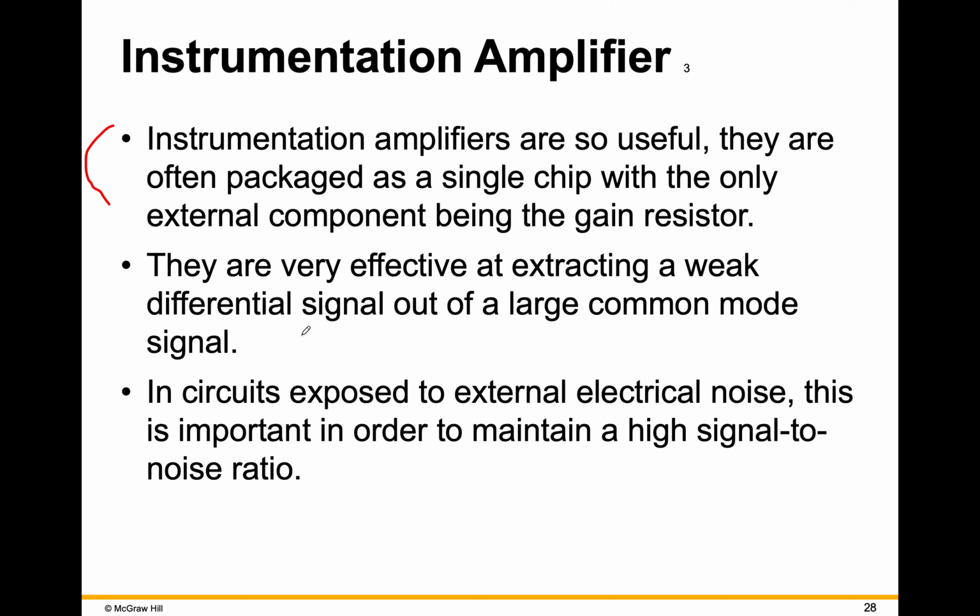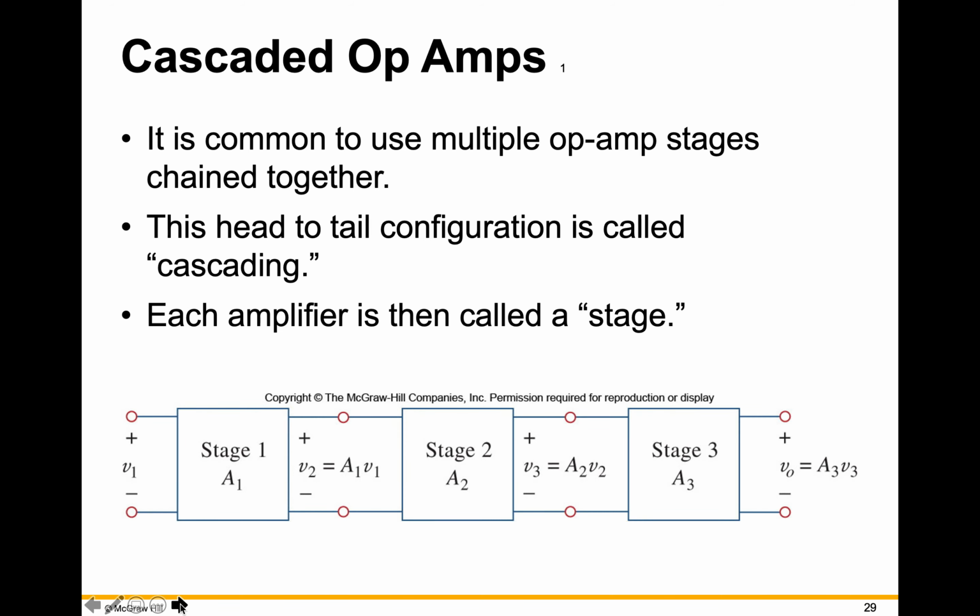So the hope is that the large signal is common to both probes, and then you can build this difference instrumentation amplifier that will take your difference and give you an amplified signal. So that's for what that's worth.